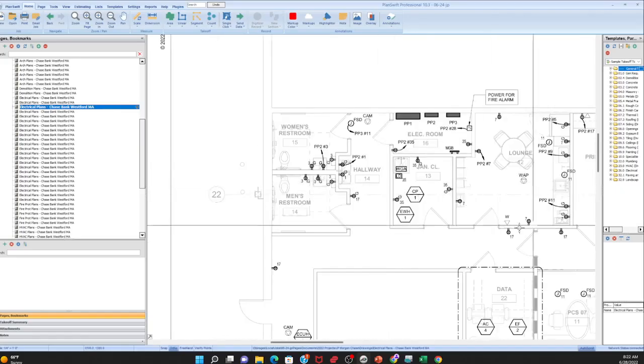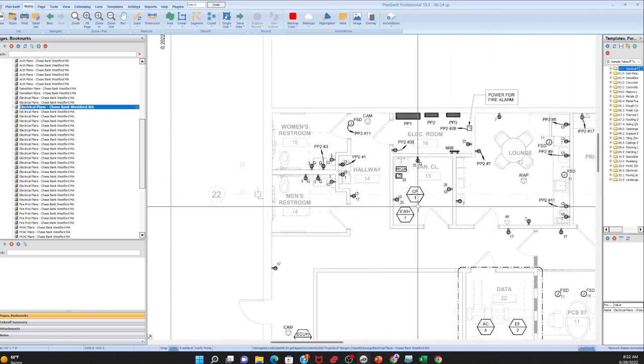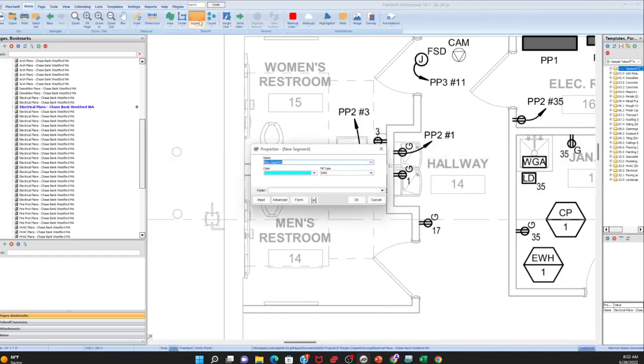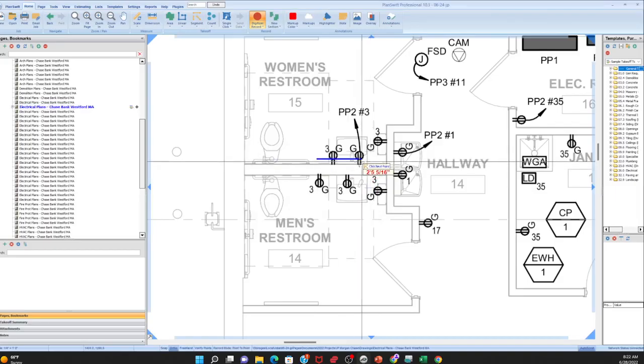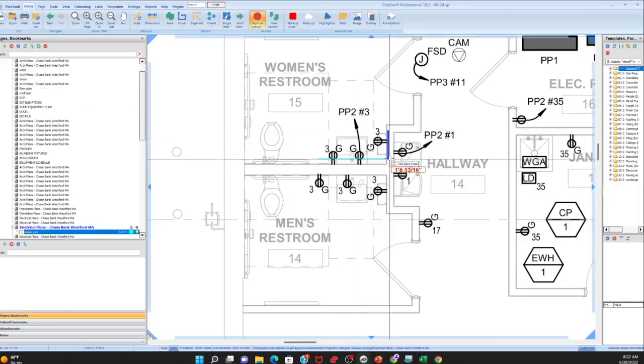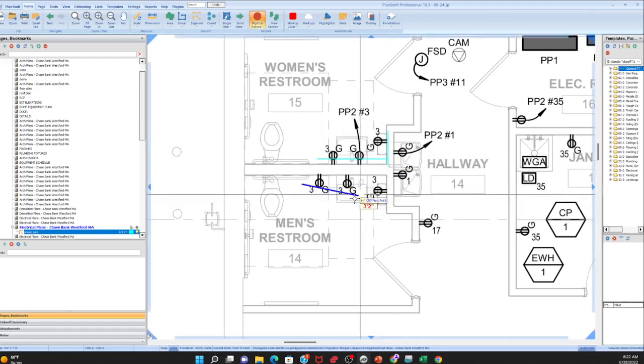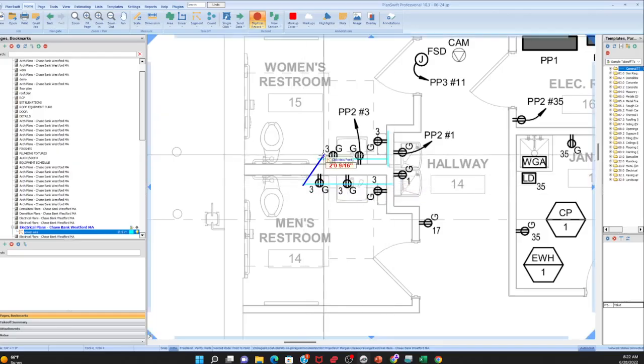Because when you do wire, you have to actually do the physical lengths of this. Now that I have scale, we have these notations above the outlet. So if they are all 3s, that means they're all daisy chained together, and I do something like this. I call it power wire. Because usually when it's daisy chained together, the electricians are allowed to use MC cable. So physically they have to connect this. So that's telling me that physically all of these number 3 wires are connected.